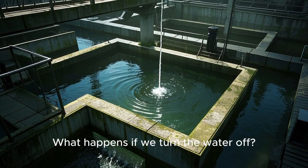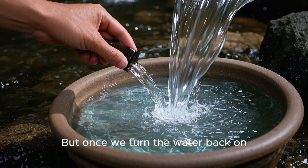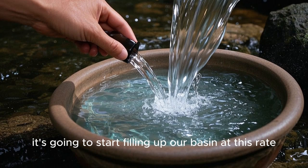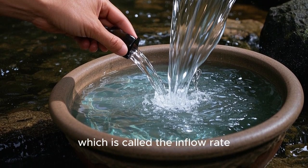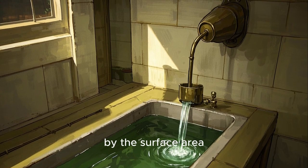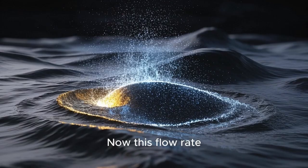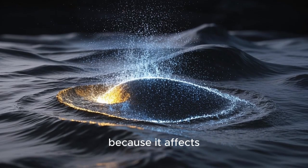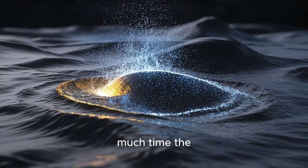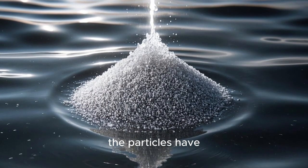So let's say we have this pipe here and we have this basin. What happens if we turn the water off? Well, the water is going to stop flowing. But once we turn the water back on, it's going to start filling up our basin at this rate, which is called the inflow rate. We can measure the volume of water coming into the basin and divide it by the surface area of the basin to find out what the flow rate is. Now, this flow rate is important because it affects how quickly we can fill up our basin and therefore how much time the particles have to settle. The lower the flow rate, the more time the particles have to settle.